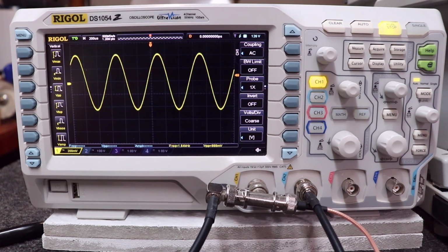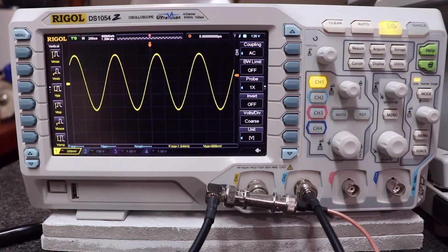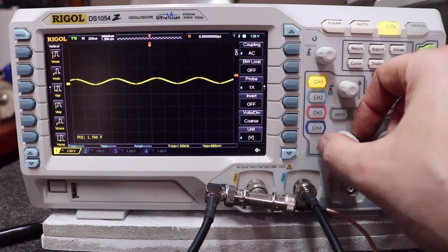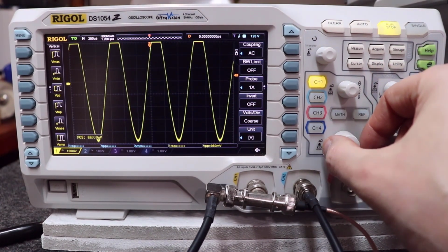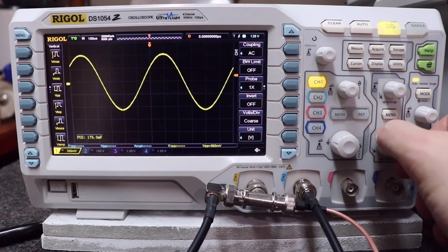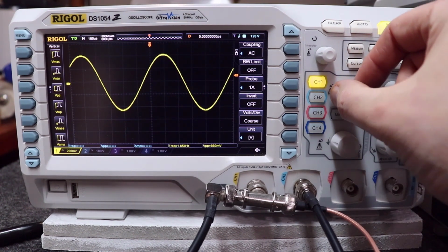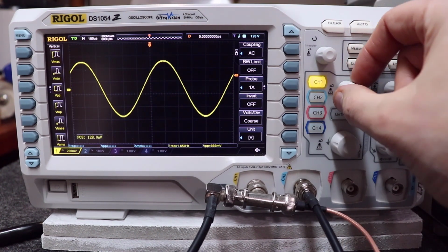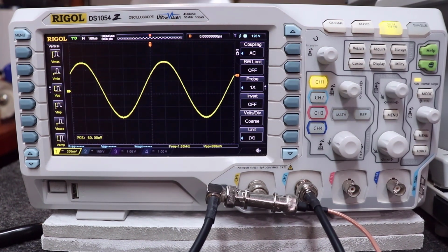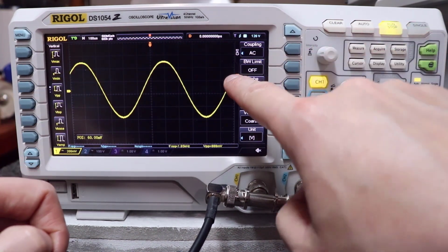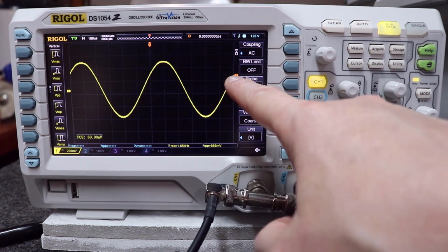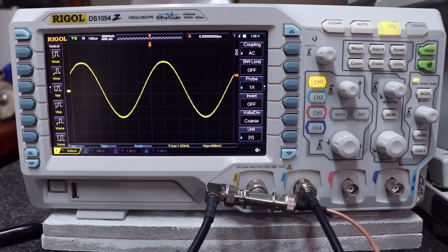But at the end of the day, you can also use it very simplistically. Just put it on channel 1. Just vary the voltage, right? Volts per division. Change the time base, right? Use the position here. It's not rocket science, and it's very similar. And by the way, you can see my little trigger level right there, that little thing on the side showing me what my trigger level is at all times.